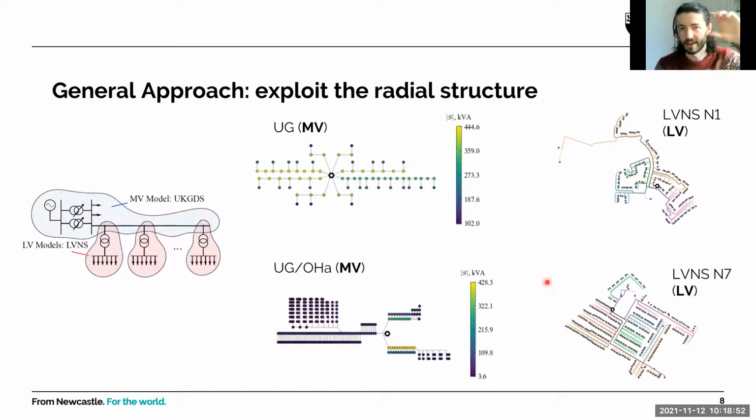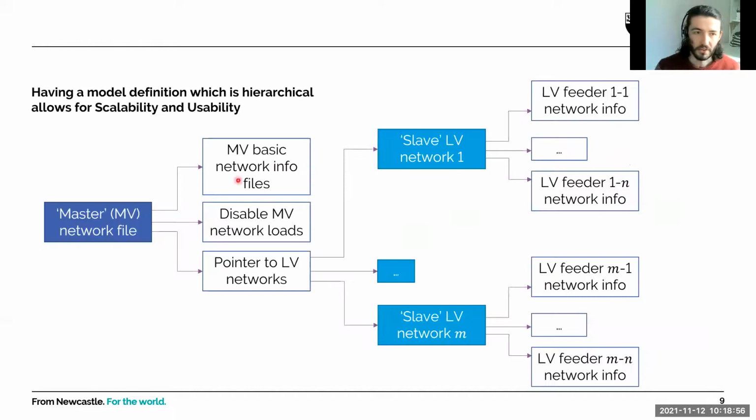Because we have medium voltage, low voltage, and then feeders, we can build that into the tree structure of the actual network model. And this is a common thing. I mentioned that 1 million node network at the beginning from NREL. If you download those, they're structured in this way, with the lower voltages going into the higher voltages going into the subtransmission.